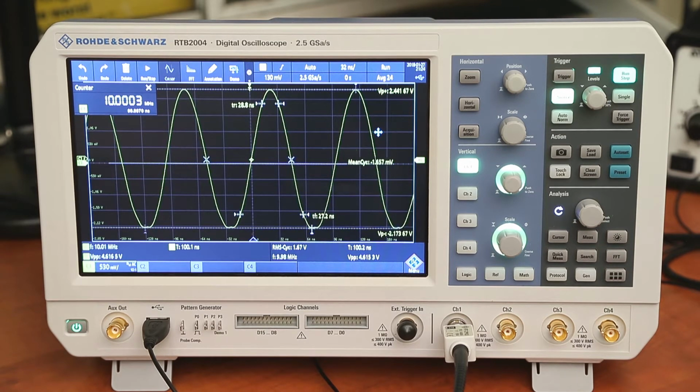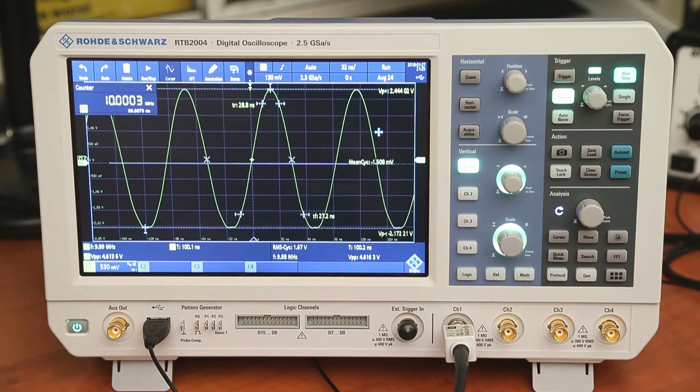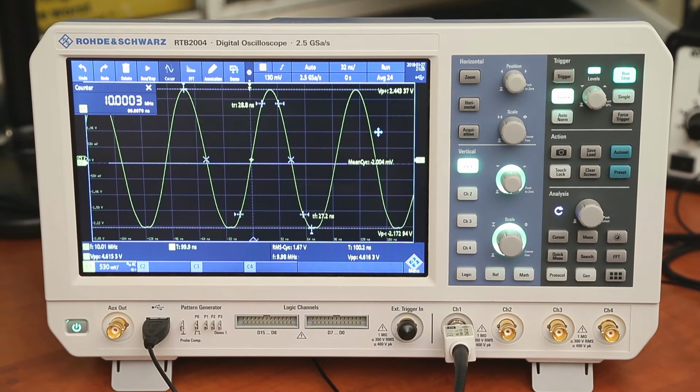So in this video I'm using that to show the standby usage in watts of this scope, and also its running usage in watts compared to my Rigol, and also compared to the Keysight, being the 2 other scopes that I have. I'm also showing in this video a 10 megahertz signal that's coming from a temperature controlled oscillator that I bought off eBay. Somebody had asked me could I just show some basic signal being displayed on both the Keysight and also on the RTB2004, just to show how the screen real estate being larger makes a difference.